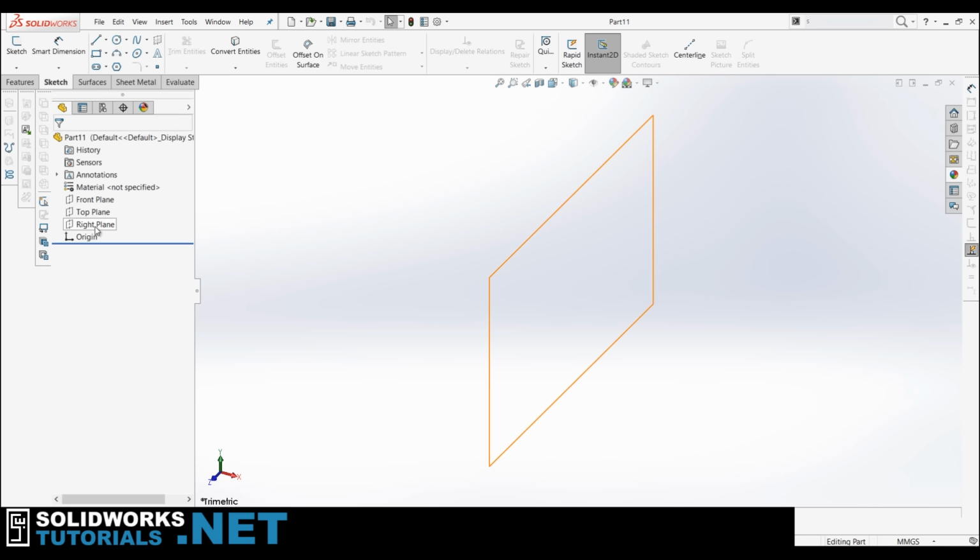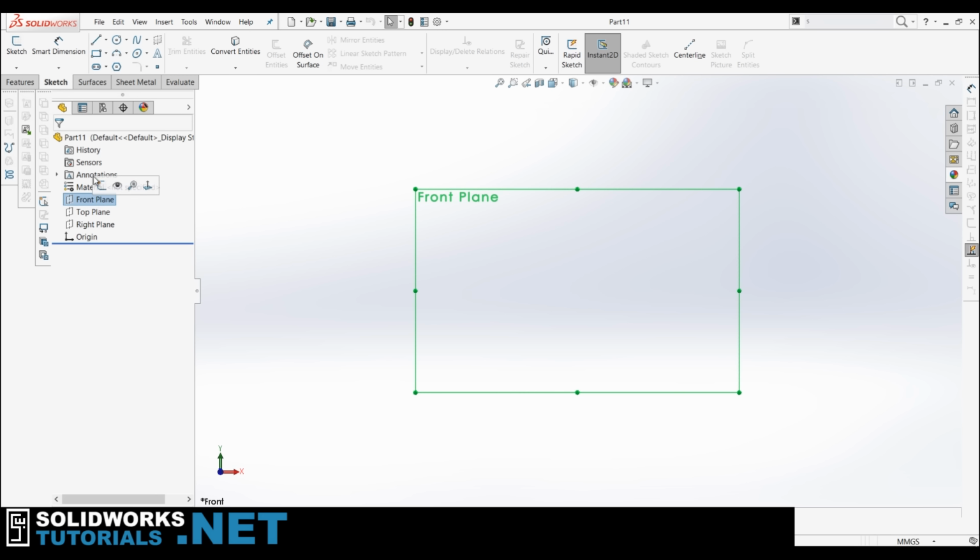We haven't started creating a part yet, so let's get to it. In order to create a 3D part, you will first need to make a 2D sketch. And in order to create a 2D sketch, you will need a plane. First things first, select a plane by clicking on one of these 3. Now we go to the Sketch tab and activate the sketch mode here. Once you do that, you see these buttons: Rebuild and Close. Rebuild saves your sketch and exits the sketch mode, and Close, well, exits it without saving anything.